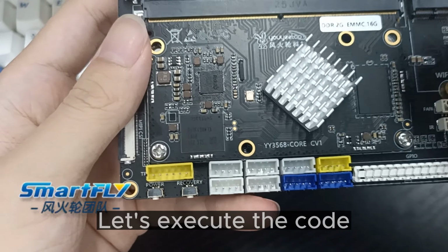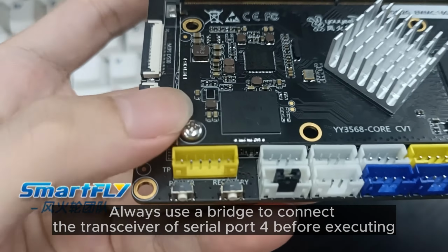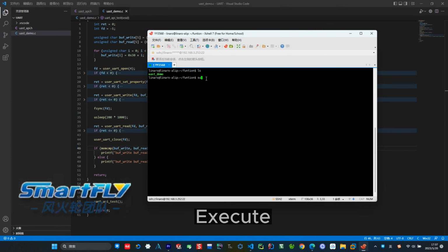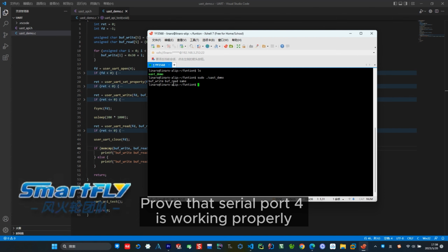Let's execute the code. Always use a jumper to connect the transceiver of serial port 4 before executing. This is the executable file that the code gets after compiling. Execute. You can see the words buff write buff read same. This proves that serial port 4 is working properly.